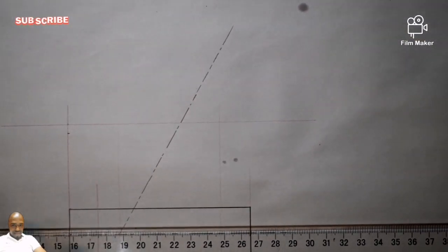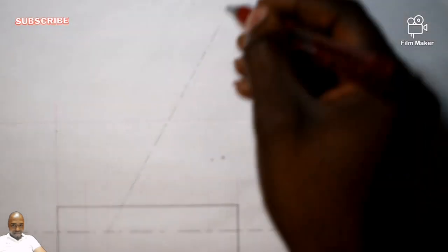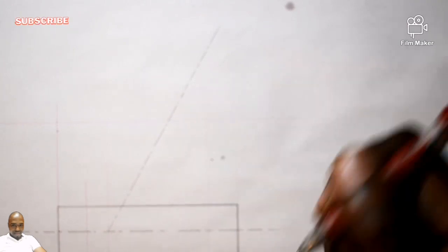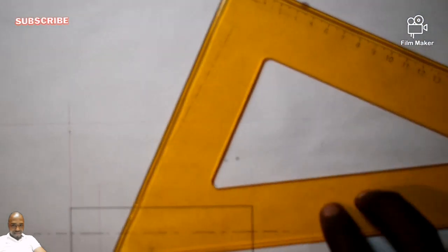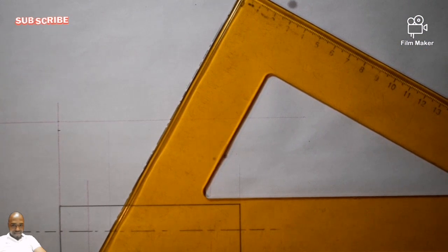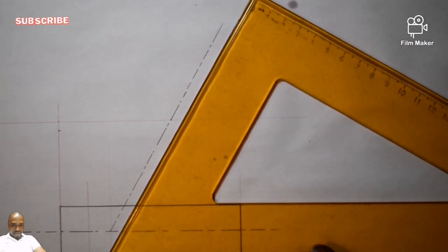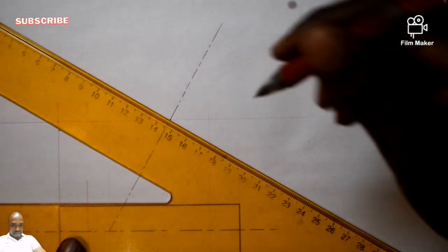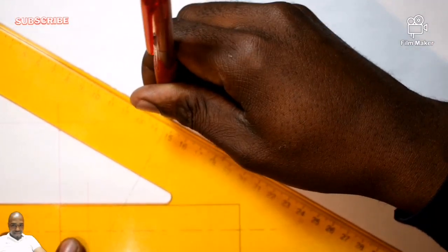You understand? If I construct it horizontally, once it touches this line of mine that is at an angle of 60 anti-clockwise, I'm going to have a point there. Then to get a center line that is perpendicular to this 60, I'm going to say 90 minus 60, so I'm getting 30, which means I have to use angle 30 degrees, so that these are perpendicular to each other.